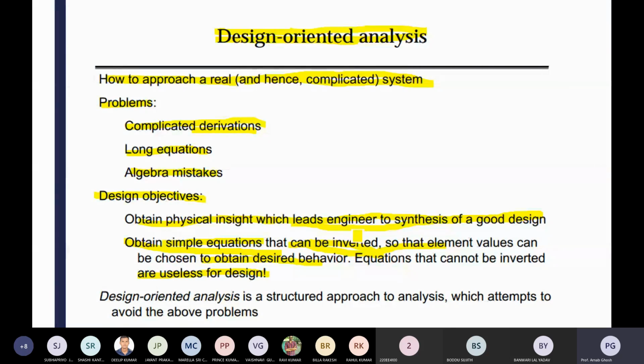But some control designs, like internal model controllers, are examples of advanced controllers. The prerequisite to design the IMC, internal model controller, is that you have to invert the transfer function.